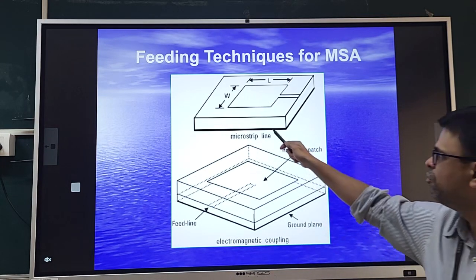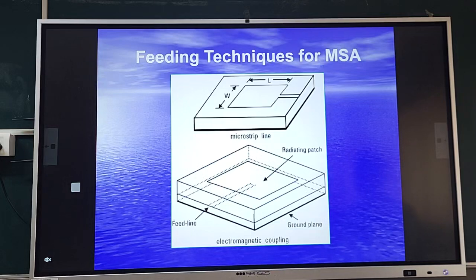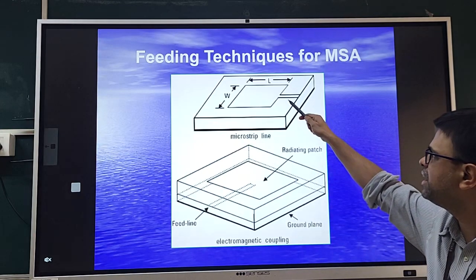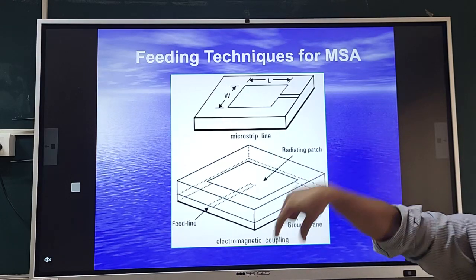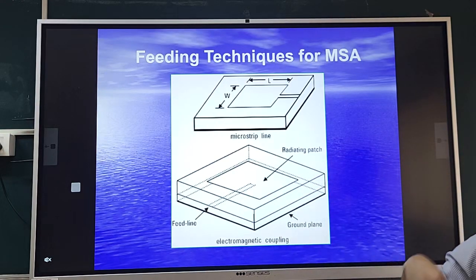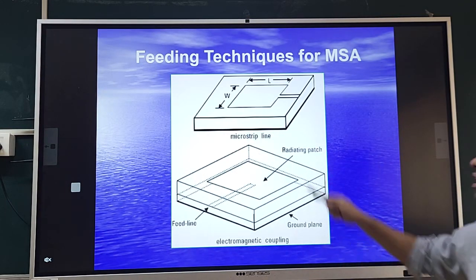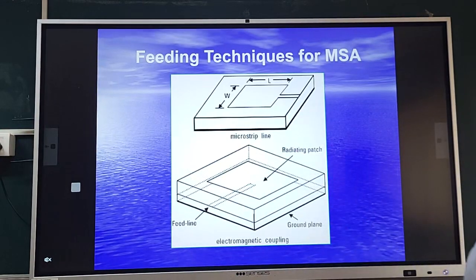So here, when I am selecting a substrate with respect to the antenna, that is a very low dielectric constant, then on the same substrate your microstrip line is residing. That is a contradictory thing for the microstrip line. A microstrip line requires a high dielectric constant substrate. In such cases, if I optimize my substrate with respect to the antenna, even my microstrip line will radiate.